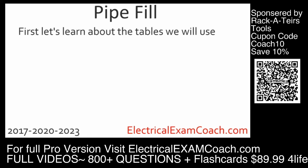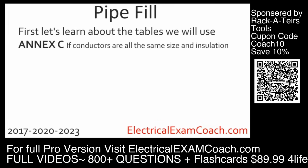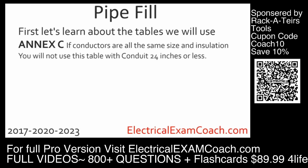Let's go ahead and learn about the table that we'll use if they are all of the same size. We're going to use Annex C. And if you've tabbed your code book, you have an Annex C tab. And if you haven't tabbed it, you can just follow along. If the conductors are all of the same size and insulation type, we get to use like a cheat sheet in Annex C. It's one of my favorite tables in the code book. You will not use this table if the conduit is 24 inches or less.